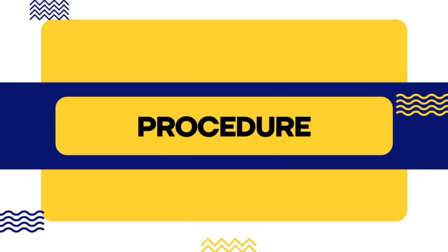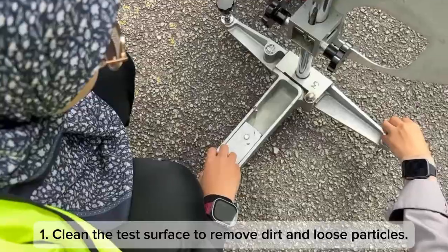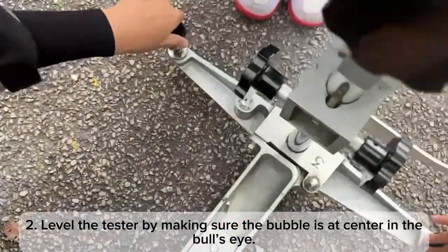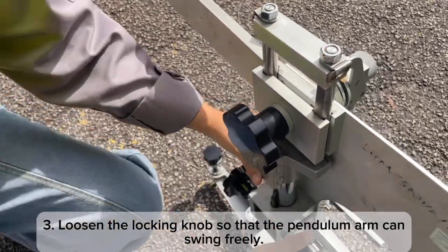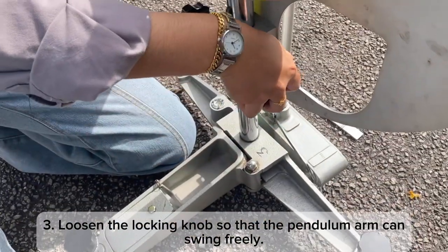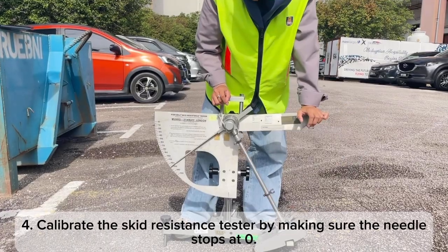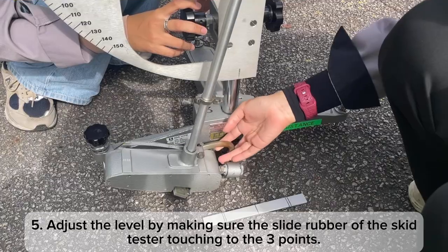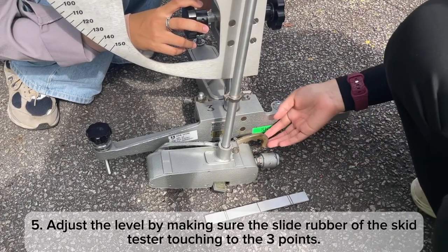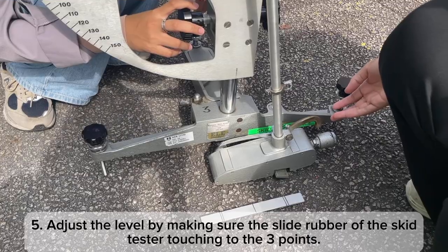As for the procedure, first, clean the test surface to remove dirt and loose particles. Second, level the tester by making sure the bubble is at the center in the bullseye. Third, loosen the locking knob so that the pendulum arm can swing freely. Next, calibrate the skid resistance tester by making sure the needle stops at 0. Then, adjust the level by making sure the slider rubber of the skid tester is touching the 3 points.